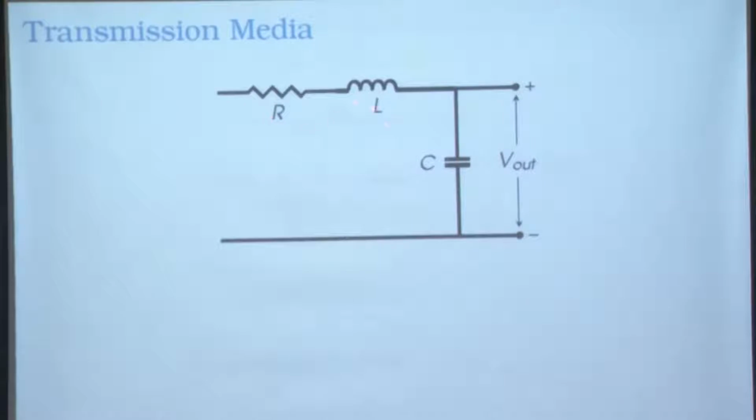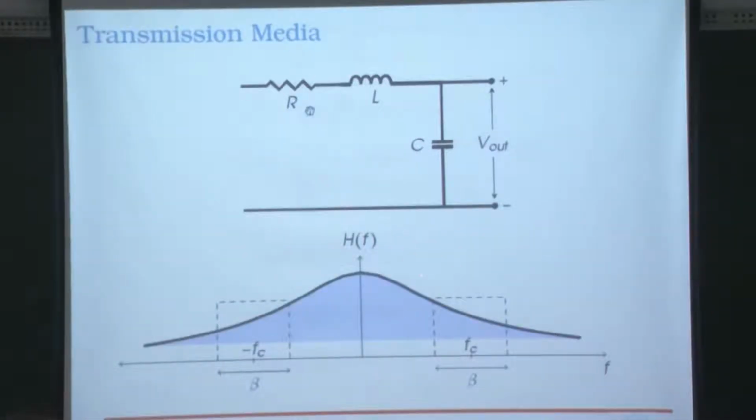So we put everything together as a lumped RLC circuit. Then we have an input and an output, and we can ask what is the effect of the input on the output, and then we will write down the model for y(t), the received signal, in terms of x(t), which is the transmitted signal. This is Shannon's idea as well. But the moment you take such a linear circuit, you know that all that is there in the circuit is governed by what is known as the frequency response of the system. At a frequency, how much is the output is what the frequency response says. In some sense, it is a Fourier transform of the impulse response that we are talking about.